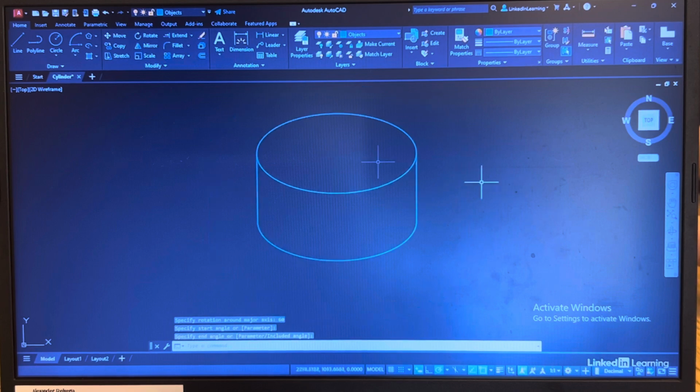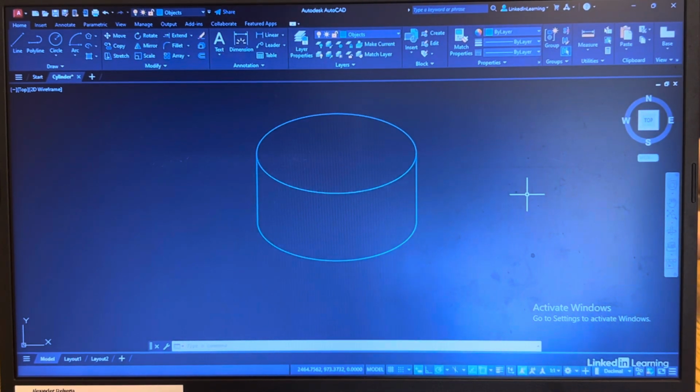Roll back a notch on the wheel. You now have a nice isometric view of a 3D circular cylinder. So it is a 2D representation of something 3D. That's why ellipses are incredibly useful, and if you utilize that rotation option and either use 30 degrees or 60 degrees, that gives you the isometric view of something that could be a 3D object.